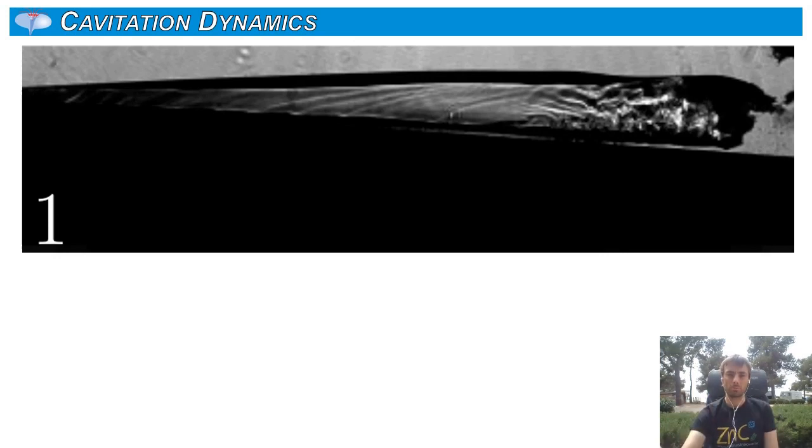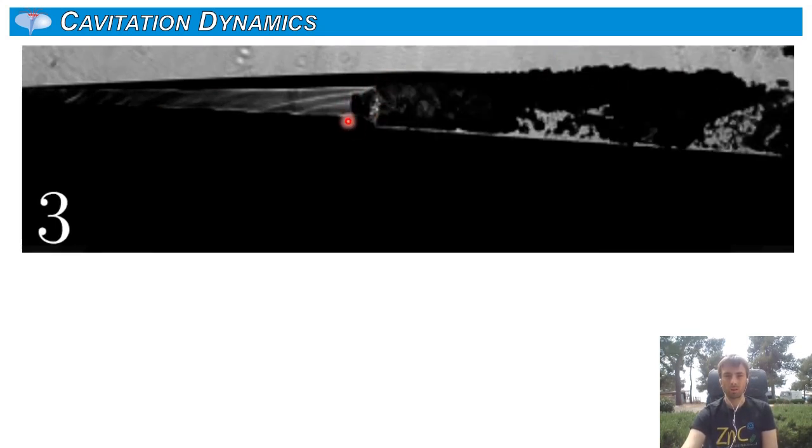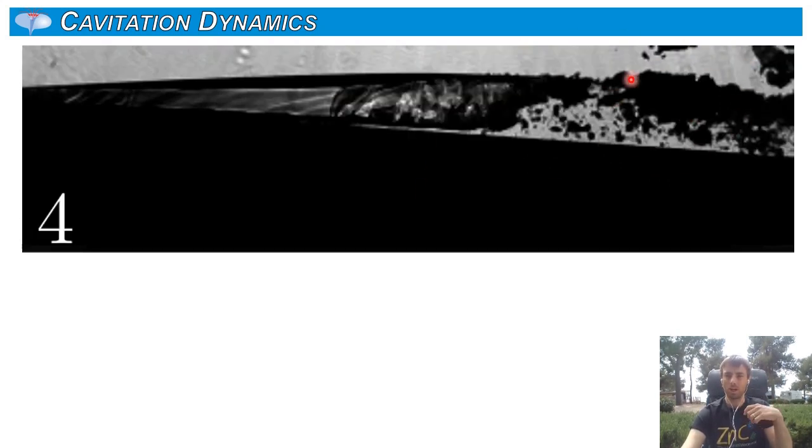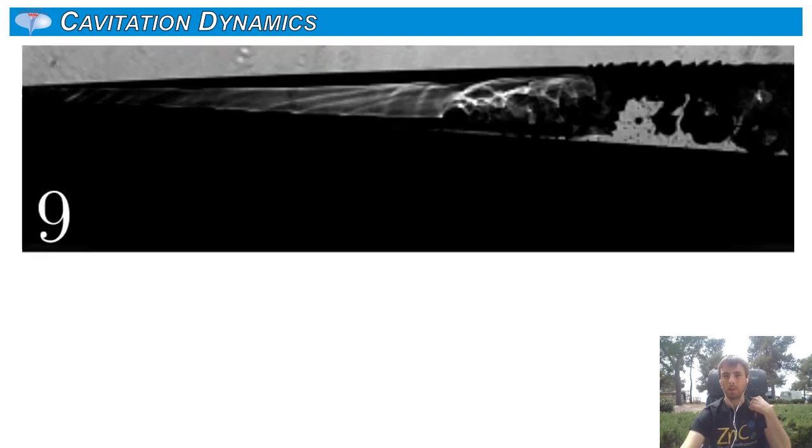To go a little more in depth, what does the cavitation dynamics look like? We have this stable cavitation pocket. Then we have an instability developing here, and this instability moves forward. It looks similar to the condensation shock observed by previous studies, but it does not disrupt it in this way. It actually grows so high that it disrupts this area here, and you have very small shedding, or very small cavities, in this area. This is what is going on. It's kind of hard to see.